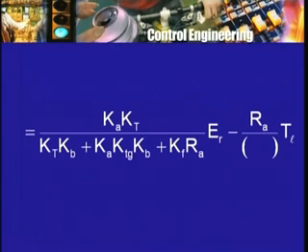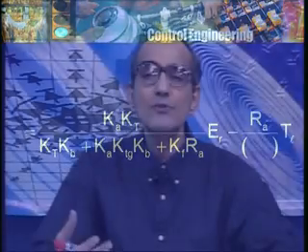However, because of this other term which is present in the expression for omega m, the load torque term, load torque changes will affect the change in speed. And if we look at what multiplies the load torque term, in the numerator we have armature resistance, and presumably the armature resistance will not change by a significant amount. The motor armature can get heated, but then usually there is a fan on the shaft so that the motor does not get heated too much, so there is some cooling. Therefore Ra is going to remain more or less what it is.